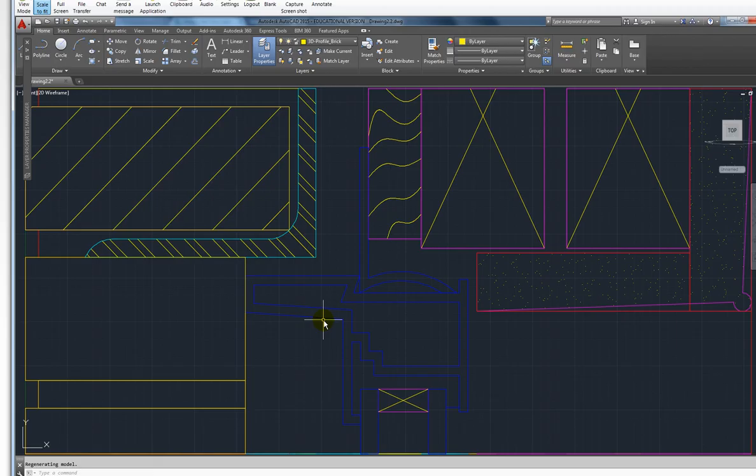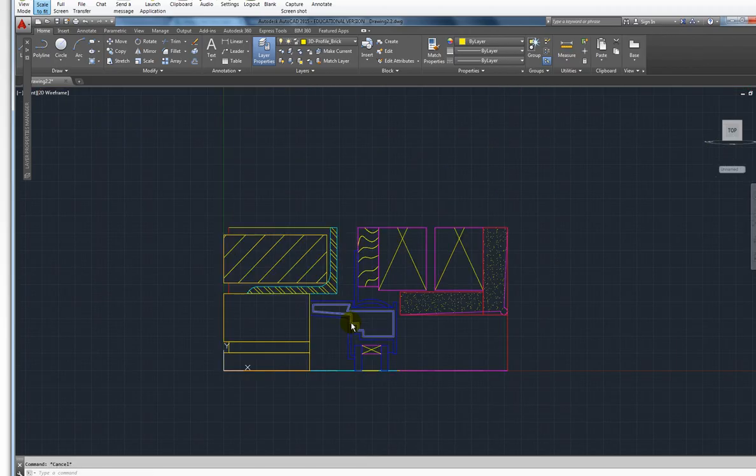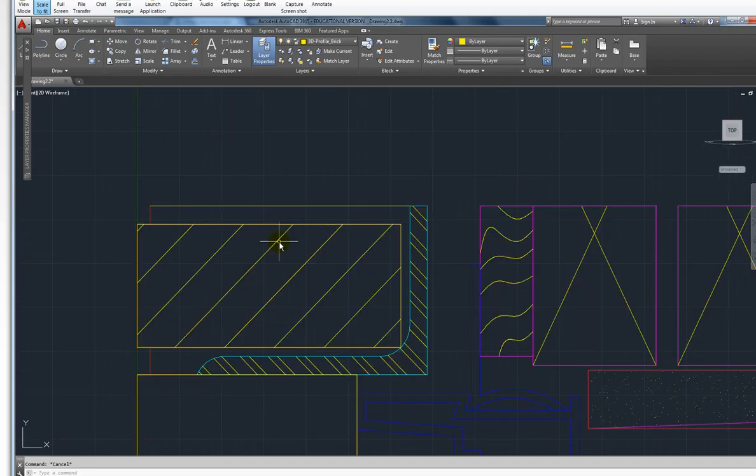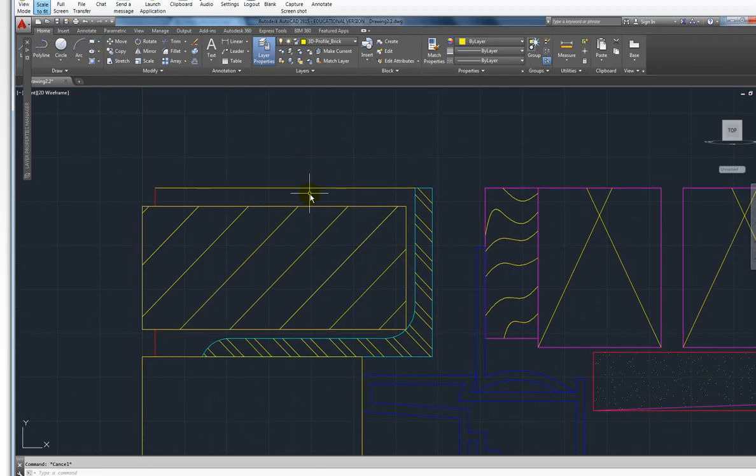Plan is going to bring us to that elevation. So plan basically takes our viewport and lays it flat, so I don't have to work in 3D. I want to work in 2D right now. But I'm working in elevation. I'm not working looking down. I'm working looking up. Okay? I think shift scroll is the same thing. Shift scroll. Okay, maybe. But just use plan. It's easier because eventually you can go to plan, world. We use plan quite a bit.